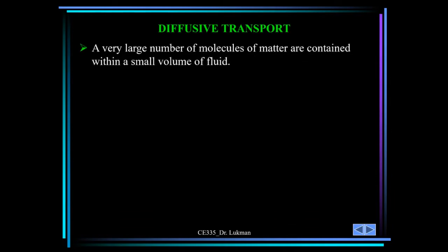I have started considering the different methods or transport mechanisms, contaminant transport mechanisms. We looked at the dominant one, which is advection, which behaves like a plug flow, where it is assumed that the flowing fluid moves with an average forward velocity, and so all the contaminants move with the same average forward velocity.